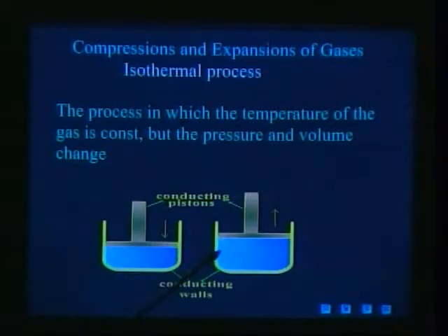Here these changes in temperature come back to the original condition because the piston and walls of the container are conducting in nature. Here in this process, as the temperature remains constant, the internal energy of the system remains constant. So, Boyle's law holds good here.